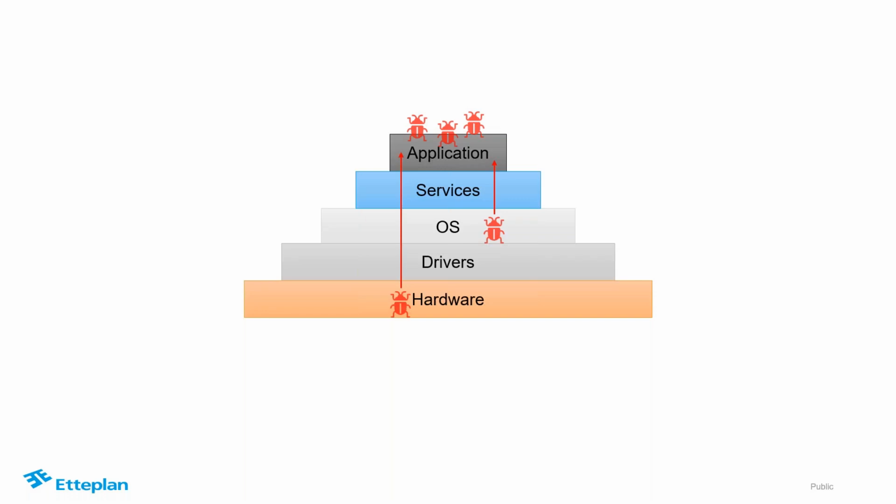Likewise, if the operating system is really well hardened, but the attacker can maybe read or even modify the flash contents on the hardware, the flash memory of the device, then they can just remove all your protections that you have placed in the operating system level, or even just again read the keys and data directly from the memory.